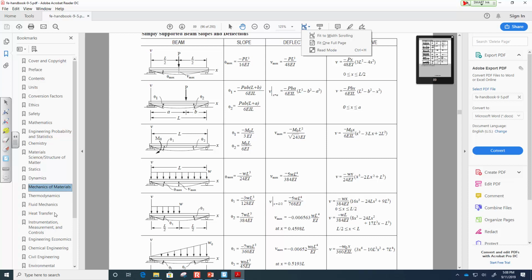For instance, if you have a beam that's like this, and it has a load on the end, you don't need to draw a moment diagram in order to determine the maximum moment and how much it is. It's right here, and it's P times L. You can just cut a section and look, P times L. So if you have to do that, the analysis will probably be pretty basic, because the point of the problem isn't really the structural analysis, it's this. Now, if you were doing the PE exam, there's a possibility that it gets a little bigger, but by then you're doing this stuff all day, every day, and it's not as bad.